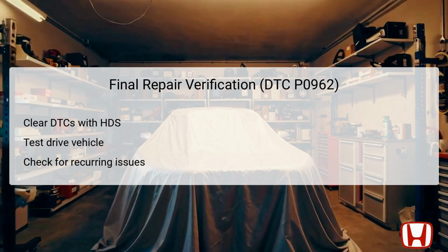After performing the repairs based on the troubleshooting steps, the final repair verification is essential. Start by using the Honda Diagnostic System HDS to clear any stored DTCs, including P0962, from the vehicle's memory. Once the codes are cleared, it is vital to test drive the vehicle to ensure it operates without any issues and that the previously observed symptoms do not return.